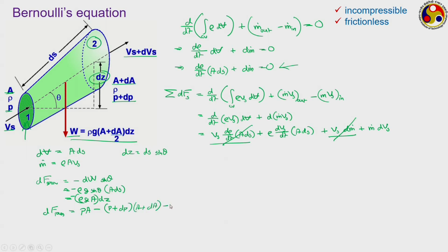Minus, we now have to consider the pressure which is acting on the periphery along the sides. But one thing we have to be careful about here: if we consider a cylindrical core and then an extended area outside of this conical section, then the effective pressure force on the side in the streamwise direction will come only from the extension of this area dA.